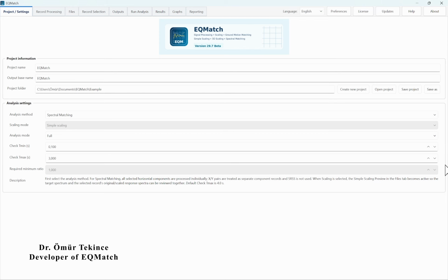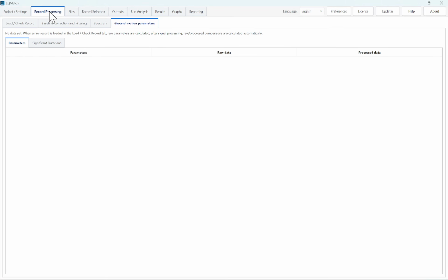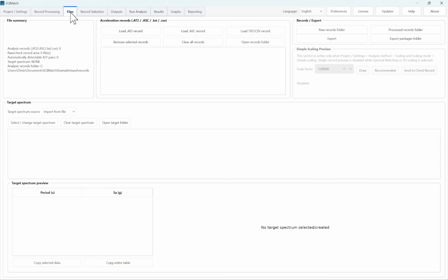Hello, I am Dr. Ömür Tekince, and in this video I will show you how to perform spectral matching in EQMatch. In this example, we will match a set of earthquake acceleration records to a target spectrum. We will select the records, define the target spectrum, run the spectral matching analysis, and review the results using graphical outputs.